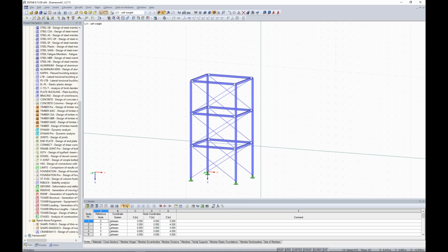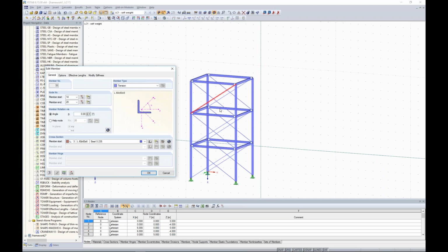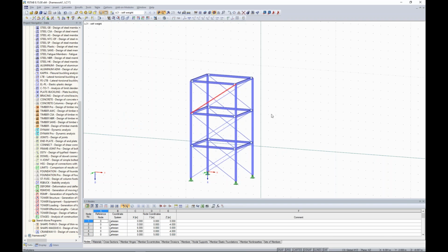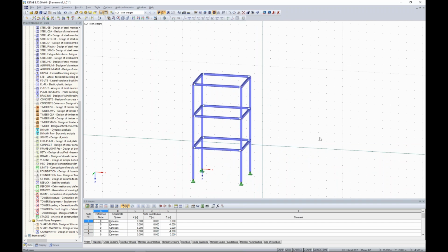So this is a very common case of tension members. You can imagine if you have self-weight load case and you calculate the first iteration, probably all the tension members have compression. And in the calculation, they will be removed in the very first iteration at the very same time. And if you imagine this exact structure with all of the tension members, let me just remove them, it's going to fall aside, and that's the instability. How can you fix it?